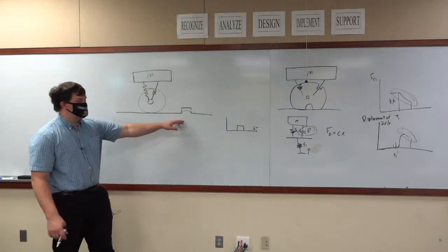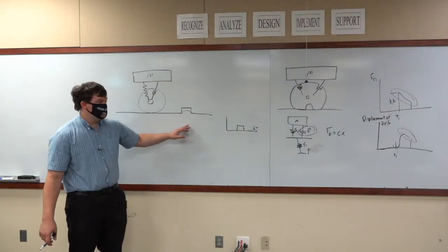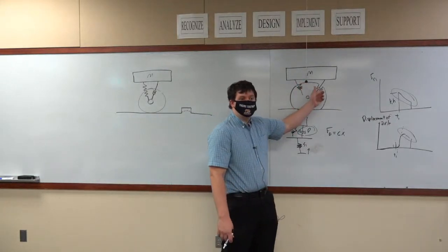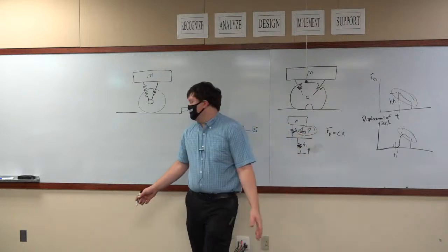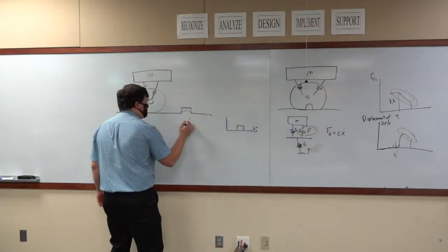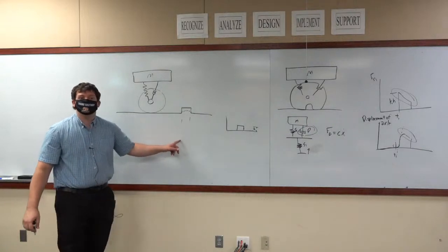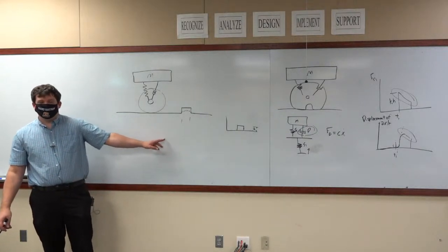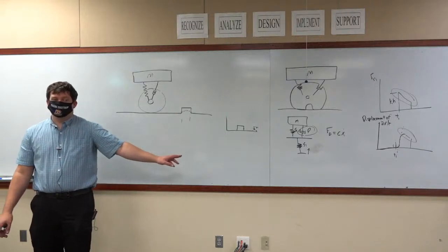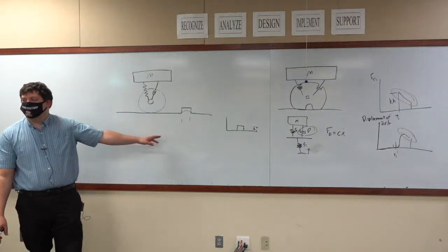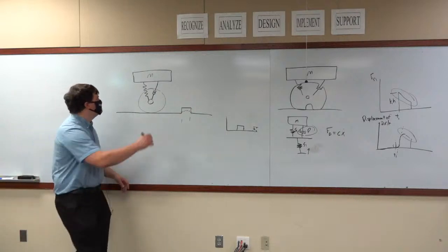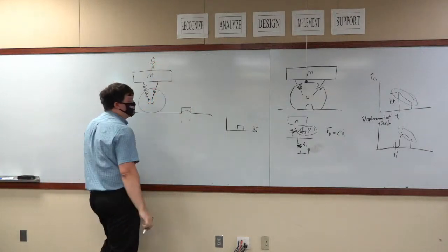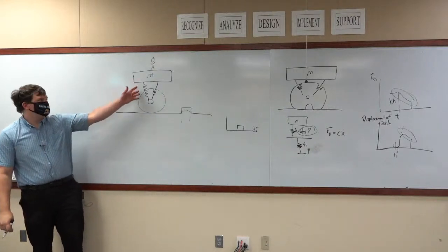If you're hitting a bump this big, you eventually want your vehicle to restore. You want the car to move upward at some point, maybe. If the bump is only this wide, your perfect suspension will have your vehicle never move up. If your vehicle never moves upward, do you feel the bump inside the car? You're standing on the mass, or you're sitting in the mass.